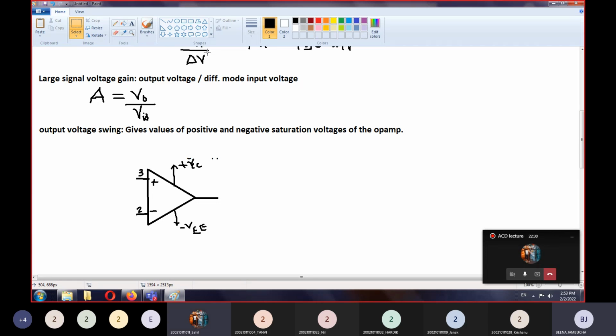A student adds: voltage between collector and emitter. Yes, right, that was VCE, which was your output voltage in terms of transistor. But this output voltage VCE cannot exceed VCC. Whatever the gain of the transistor, your output will not go beyond VCC.